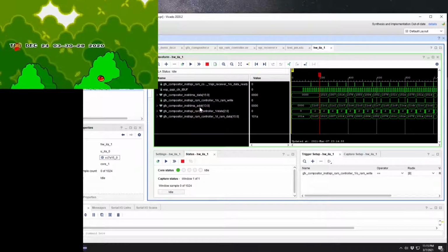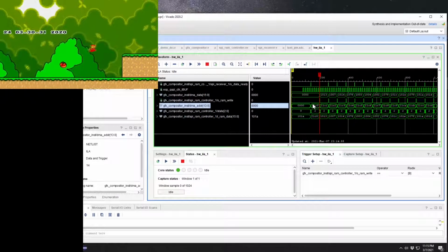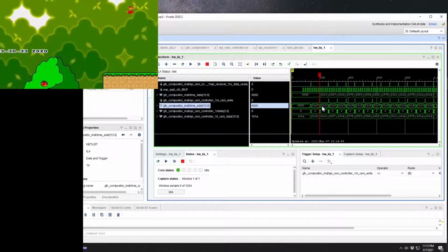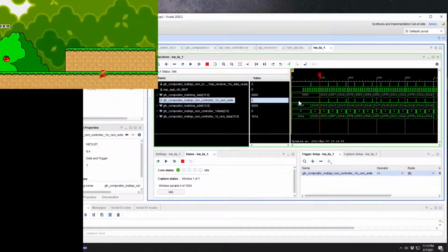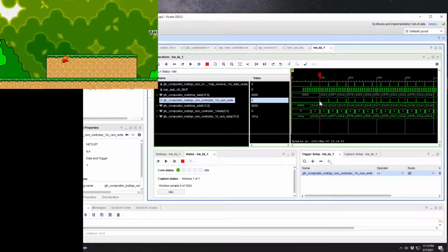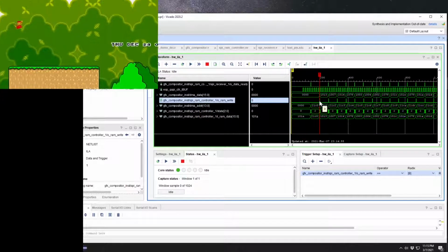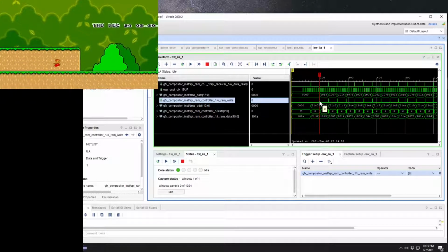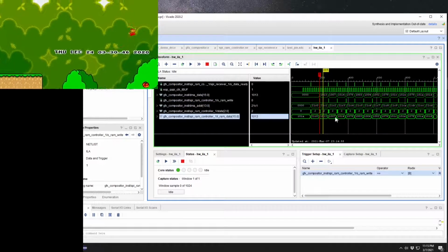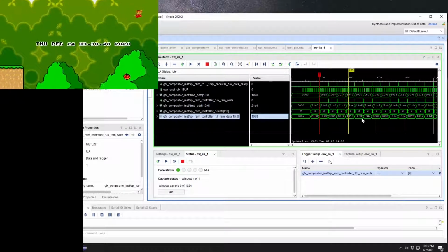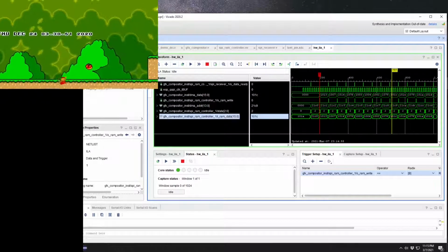So here you first see the address. Like I said, we start at 21C0, like you saw in the ESP32 code. And every time output RAM write pulses, it's a signal that the data is there, the address is correct, and the data is correct and ready to be written to RAM, right? That 16-bit word is ready to be written. So you can see we go 1013, 1007, 1014, 1078, and so on all the way down. Just as a reminder as to what that means.